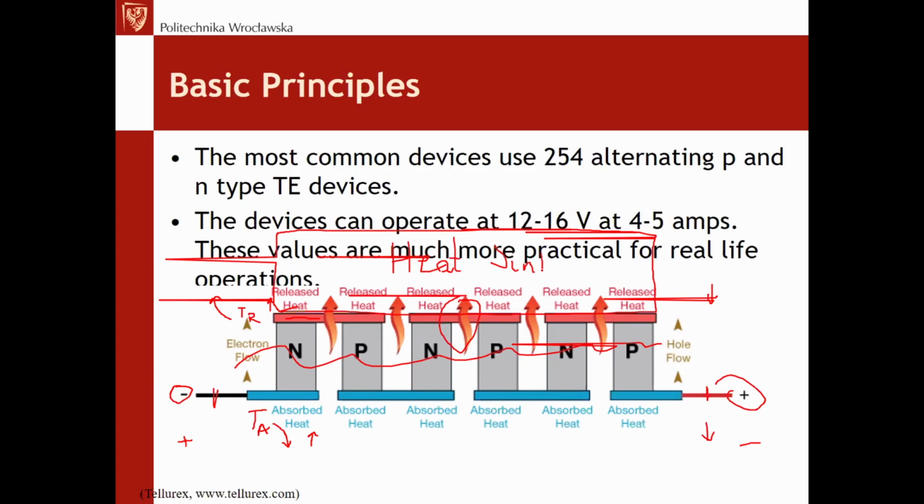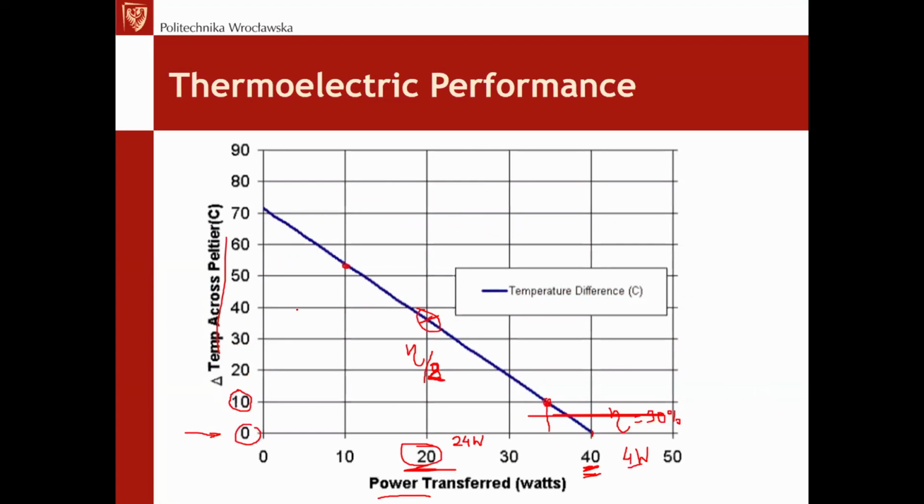The role of the heatsink is the reduction of the thermal resistance of the hot side of the Peltier element, and dissipating as much heat as possible to the ambient or to the destination. So don't forget about it.